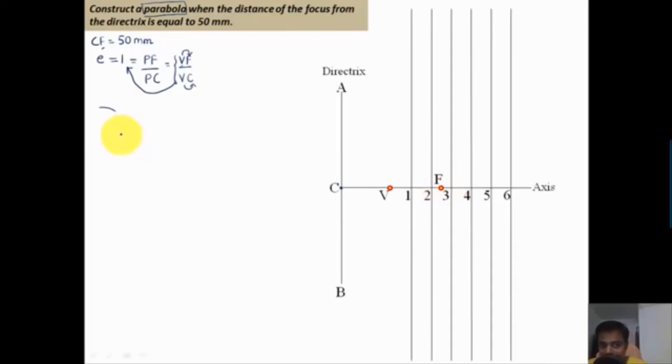Alright. Now the next step is extremely important, and I would suggest you all to note this down. Okay, so you're going to have to take arcs of radii. Note this down, arcs of radii. The first arc that we're going to take is C1, second one is going to be C2, C3, and it keeps on going. Okay, and I have as many as 6 points, so we have to reach up to C6. Alright, all these arcs have to be put up taking F as the center.